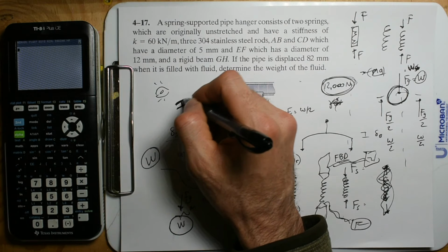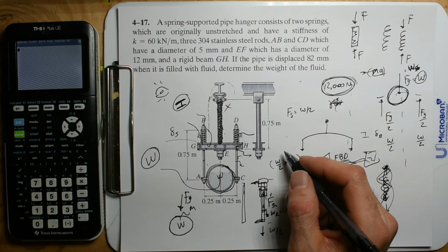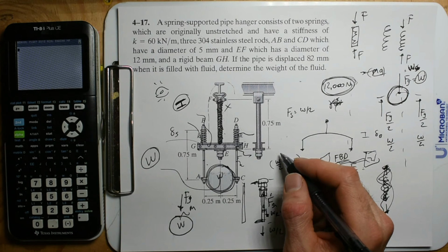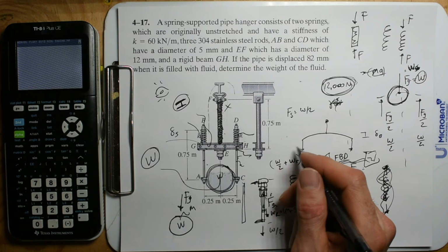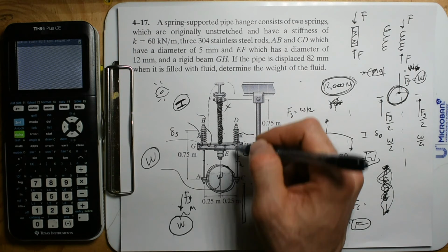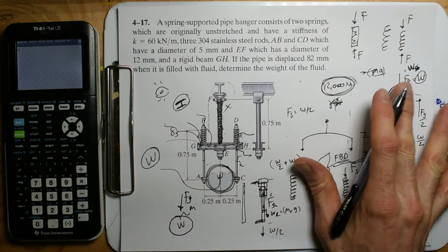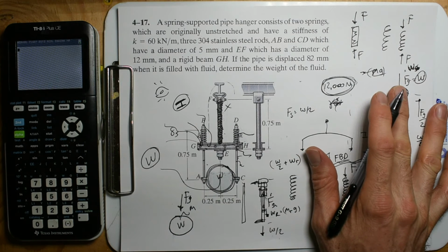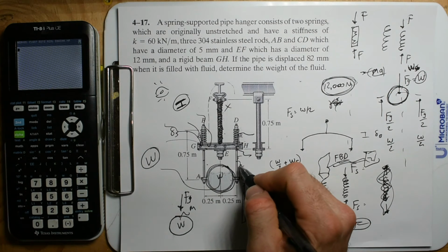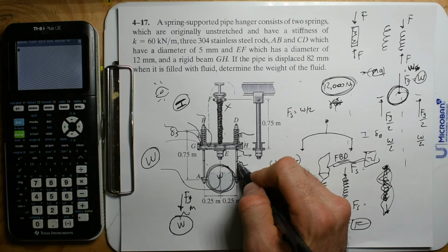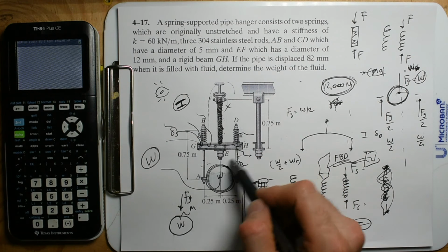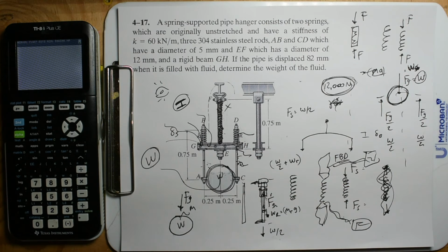I think you just need the moment of inertia of that beam, which they don't give. So we can't figure out deflections in the beam. So we're just going to assume the deflections in the beam are totally negligible, and that there is extra deflection in these three rods. So that's where this problem is going to be.